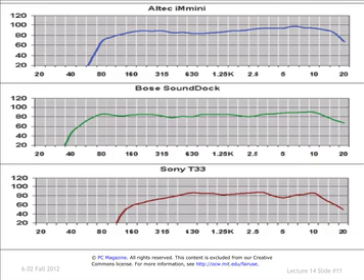So let's take the Sony speaker, for instance, down here. Okay, so it's got a fairly flat frequency response for a range of frequencies, but you've got to get fairly high up before you get there. For frequencies lower than about 100 hertz, this is not doing a very good job of propagating the sound. The frequency response is measured by having a microphone at a fixed distance from the speaker in an anechoic chamber. And you can see that this one is actually perhaps the poorest of the speakers, in that it does very poorly with the low frequency sound.